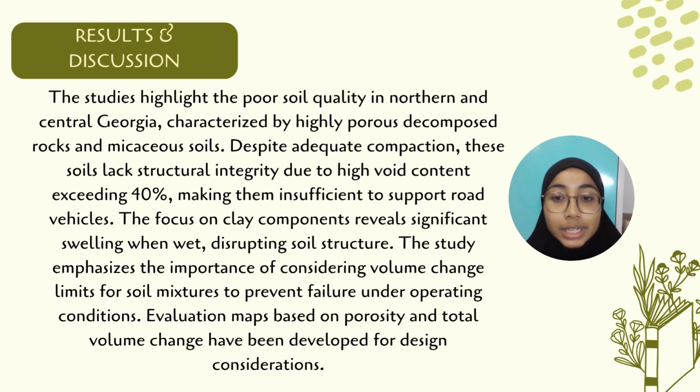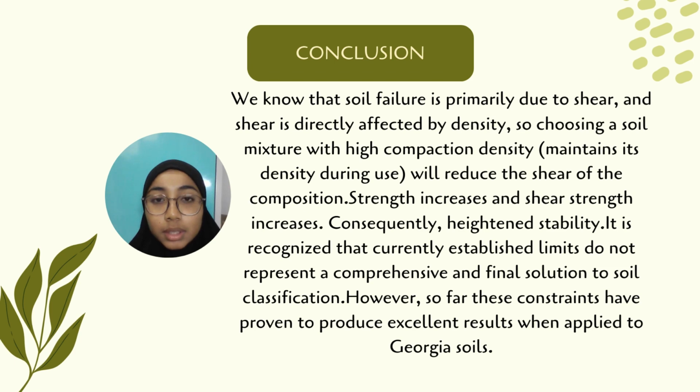The focus on clay components reveals significant swelling when wet, disrupting soil structure. The study emphasized the importance of considering volume change limits for soil mixtures to prevent failure under operating conditions. Evaluation maps based on porosity and total volume change have been developed for design consideration.